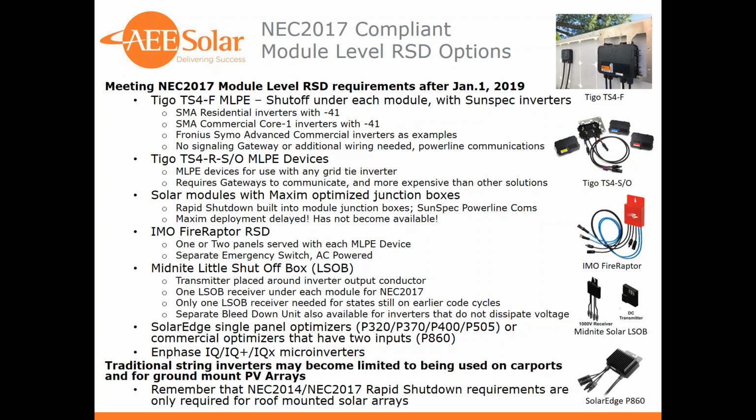Other ways of meeting that is go with a solution that brings the power electronics up there and is integrated with the system. So SolarEdge, their inverters and their optimizers, all of the single panel optimizers in the residential line could be used for commercial. So your P320, P370, P400, P505, you have to make sure that the optimizer works with the module you're considering using with wattage and voltage and current.